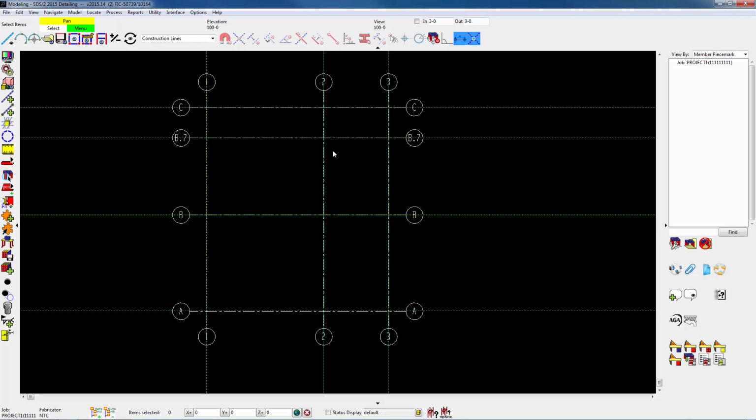So the construction lines that we put in are not completely necessary to put all of them in. If you put in grid line 1 and A, construction line is enough to get that in. You can base all the other construction lines off from the previous one. That ends the lesson on how to add your first plan view and your elevation views.